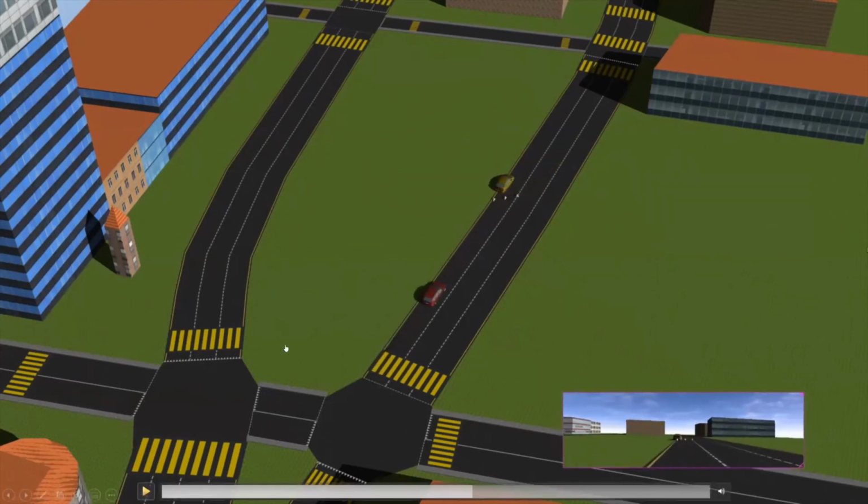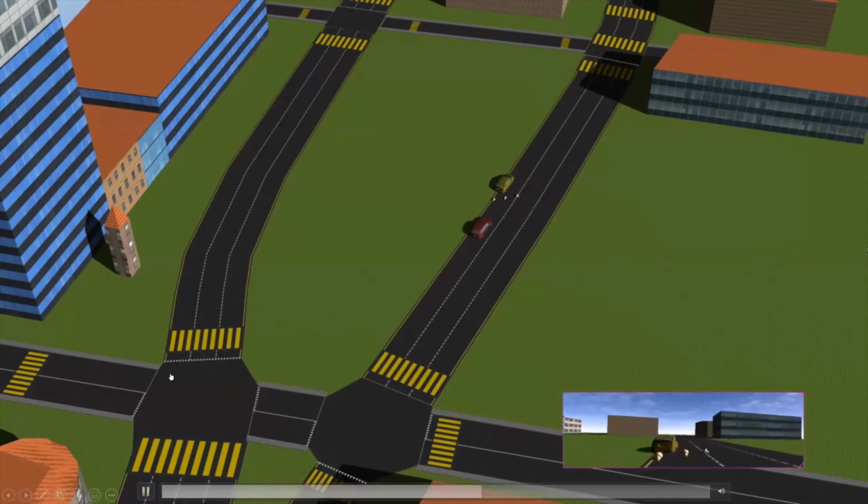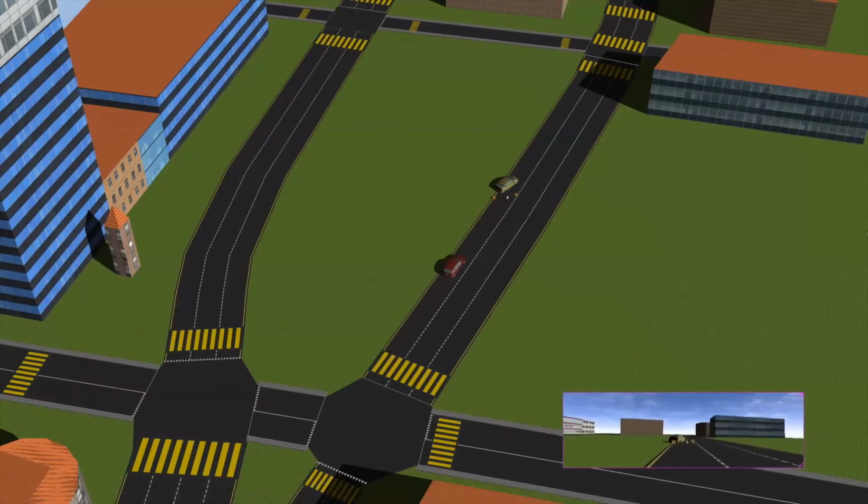And what's really happening here is Scenic every time is changing the initial position, the initial velocity, the color, the model, things like that. It's changing various parameters while getting closer and closer to the obstacle. Okay. And you can see all of these are collisions. And it's producing a varied set of counterexamples, really.